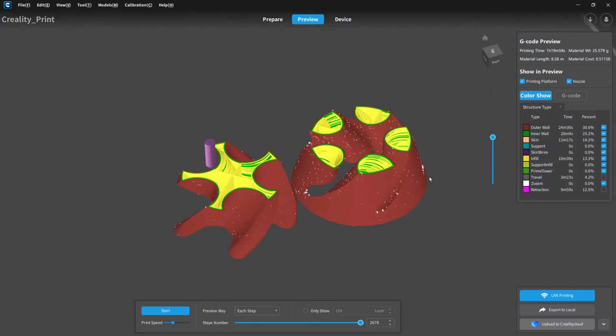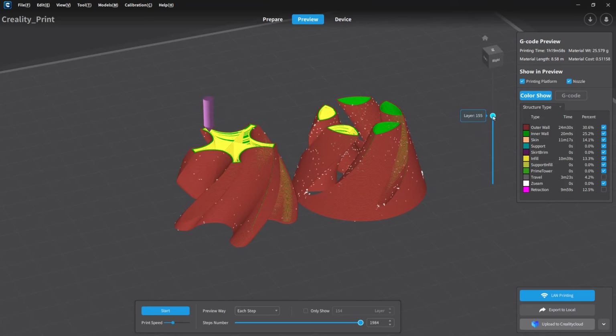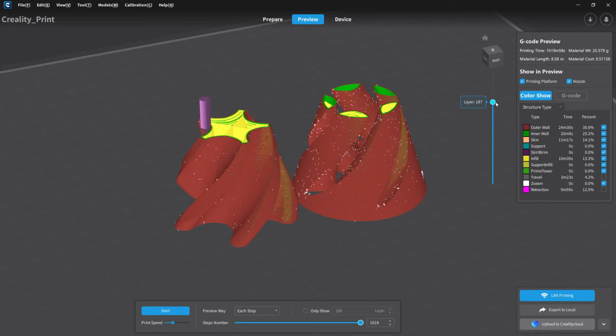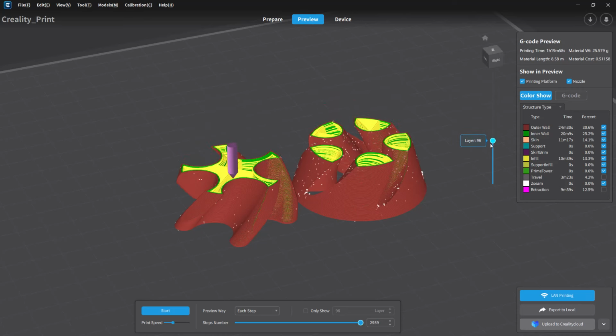But you can see as we go up, even though we've got these angles, it's just going to build each layer as it goes. It's going to be using supports on the inside with, well, not supports, but a pretty sparse infill. At least in this case, I do about 5 to 10%. And that's perfectly fine for this.